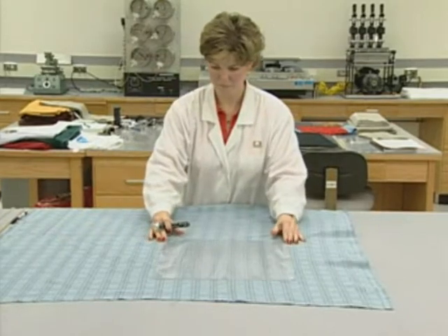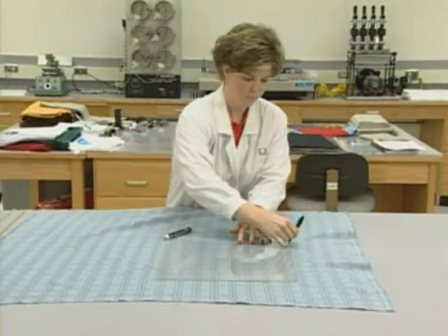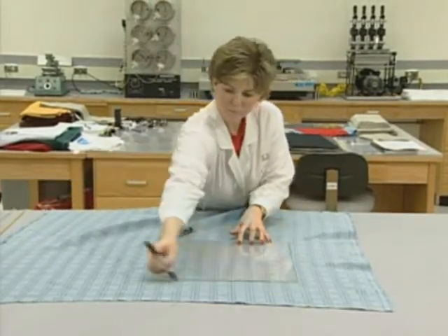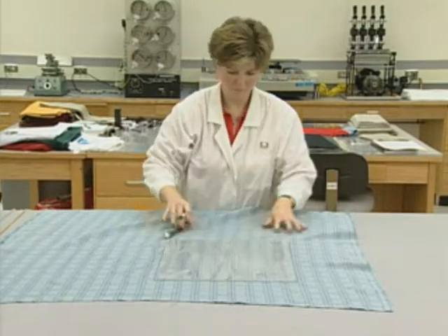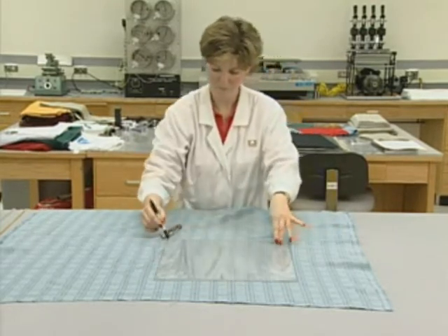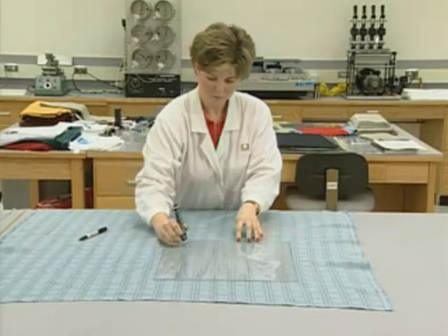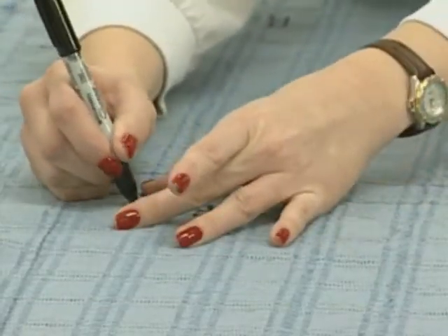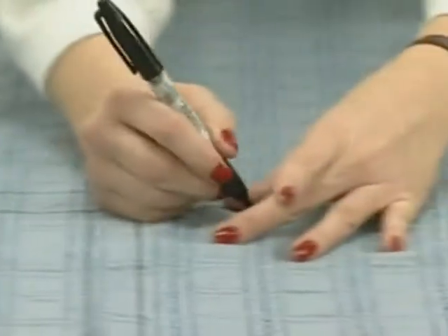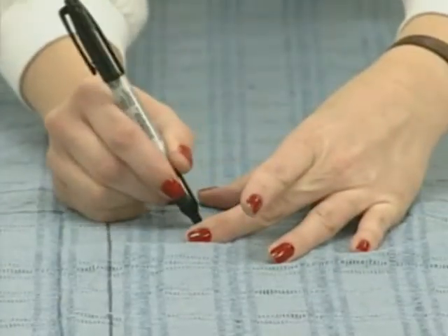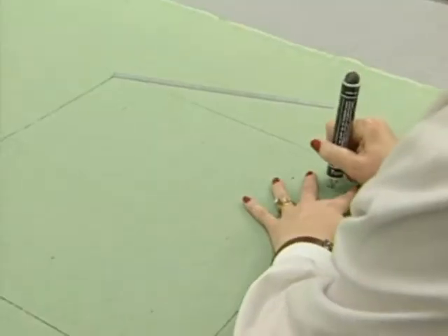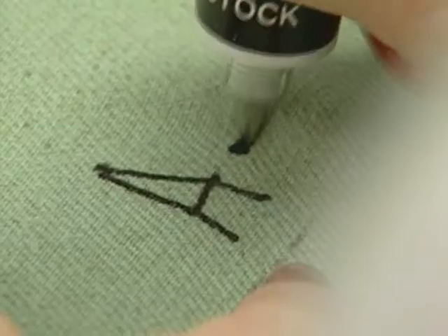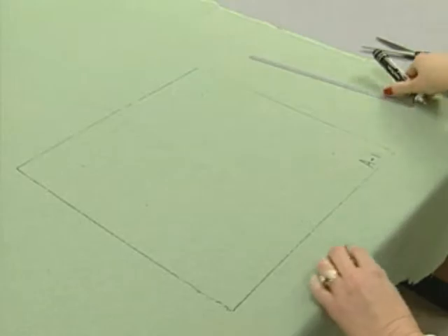The subsequent 2 specimens must be located so that different warp and filling yarns in wovens or different courses and wales in knits are included in the test. If enough fabric is available, then the specimen should be laid out in a diagonal across the width and length of the fabric. If not enough fabric is available, then an L-shaped pattern should be used. Label each specimen with proper identification so it's always read in the length direction. The identification can be a combination of numbers, letters, and symbols.